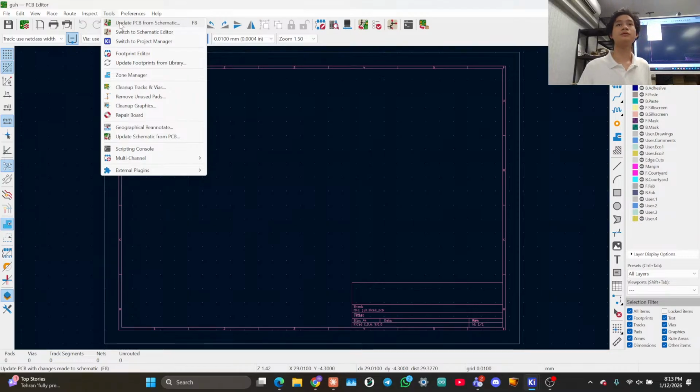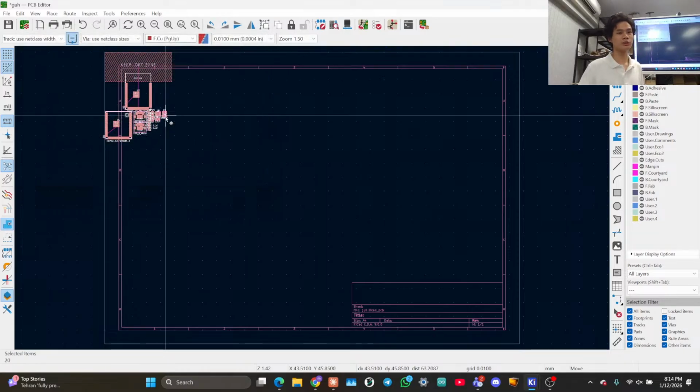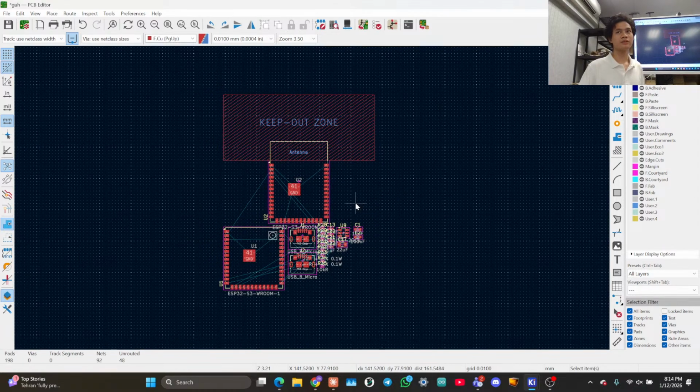Is everyone able to find this? Yeah, so it imports all the footprints. So press update PCB, and if it doesn't work, let me know, but it should work. And then go to close. Then just place wherever. How do I add the footprint halfway through all these things?